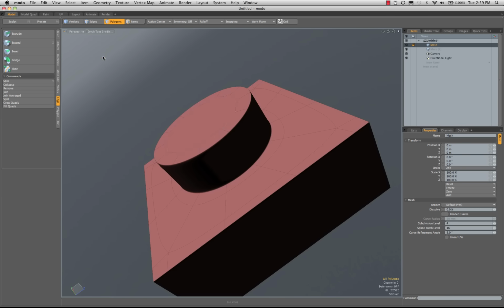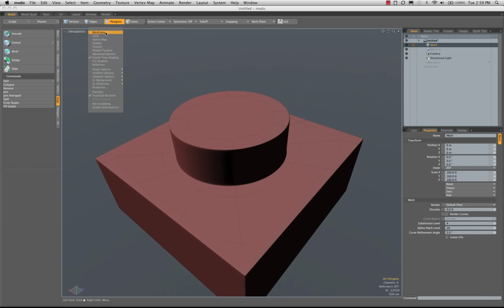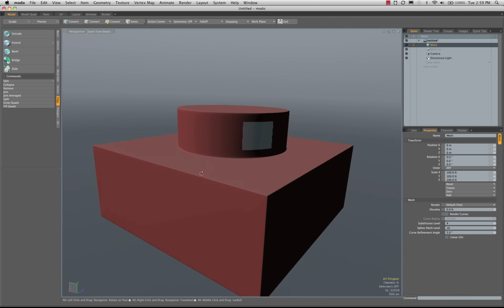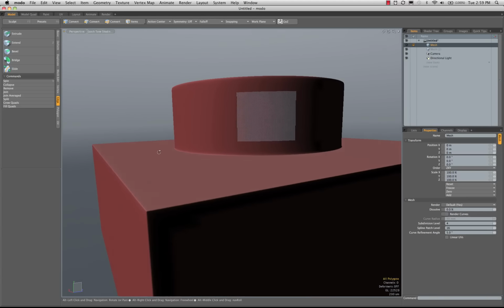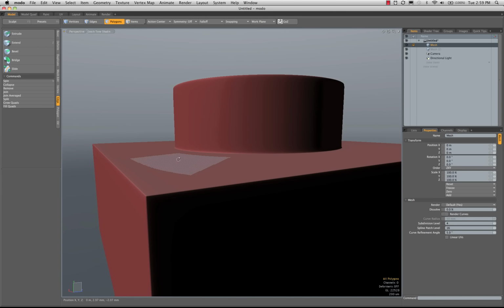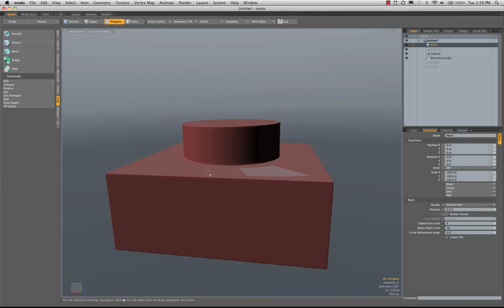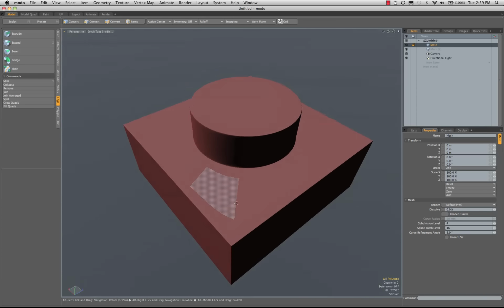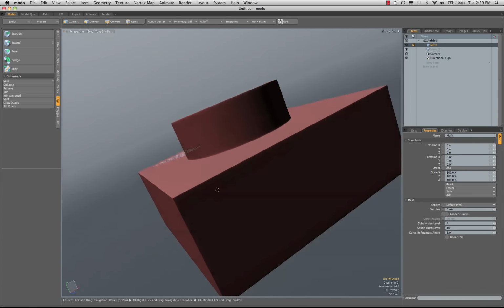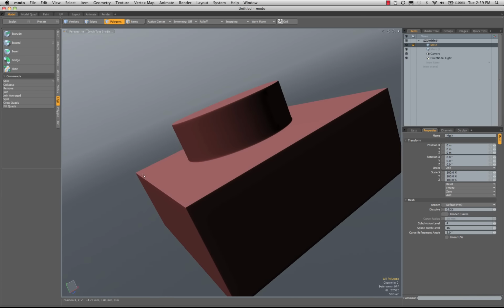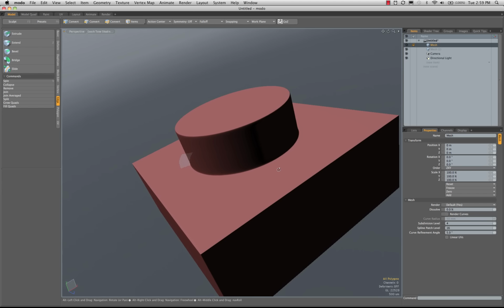You can also use the gooch tone shading, which I have updated using a different gooch tone. You can do a search on the forums, and there is a replacement. It's very simple to do. So you can also use that to kind of see contours and make sure that everything's flattening out nicely. If you get a constant color, you know that you have a flat surface.